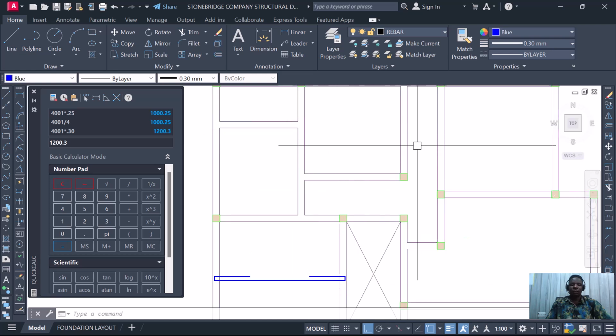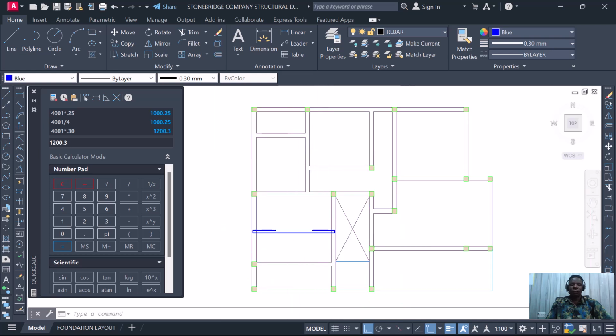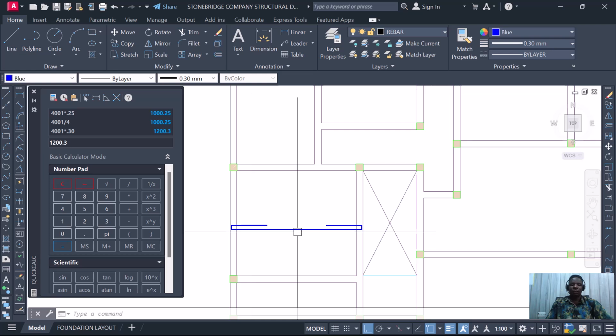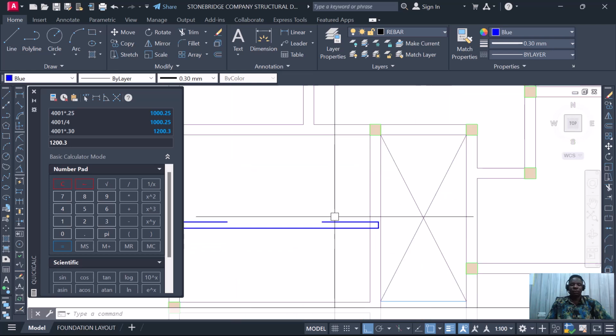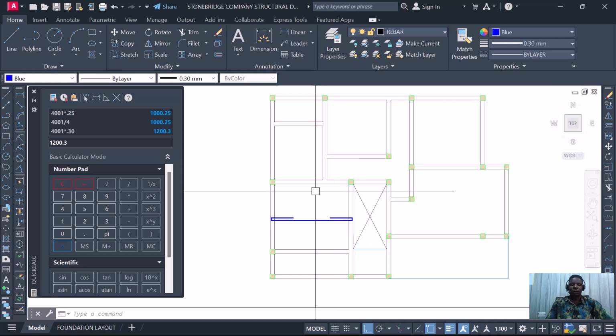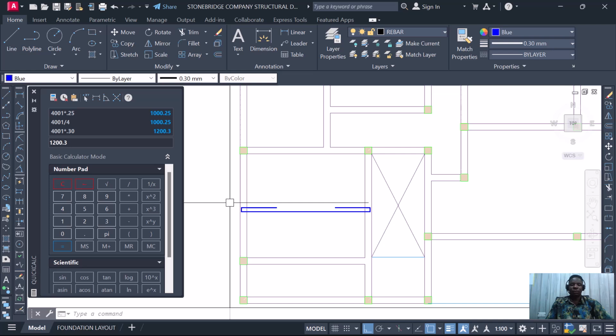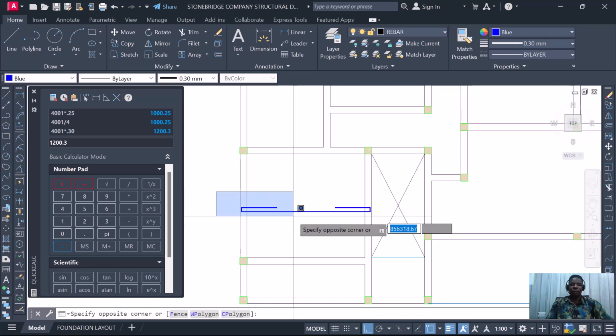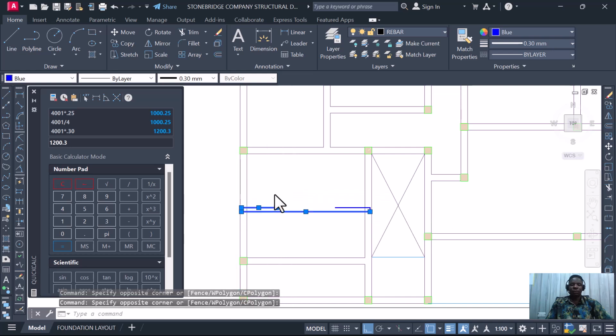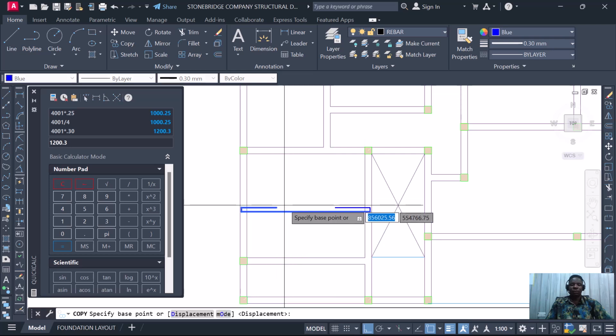The same policy goes in the joint, even when you're doing your top bar length. This same percentage is also applicable to it. When you're doing your top bar, you look at this span. The top bar length for this side should be 25% of this particular length as the extension length for the top bar. The same thing applies to this other side. So all these are just the extension length.